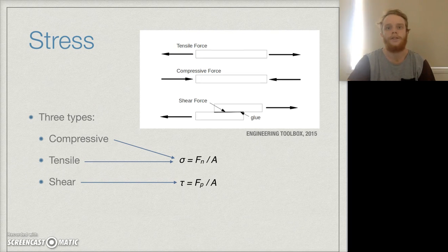Focusing first on stress, it can be defined as the application of a force to any face, internal or external, of an object, and is expressed as force per unit area. For example, if you take a piece of string between 2 points and draw it taut, then you are applying a force relative to the cross-sectional face of the string. This force can be said to be causing stress in the string, which logically, when the stress reaches a certain point, will cause the string to snap or fail. This particular example is of a tensile force.